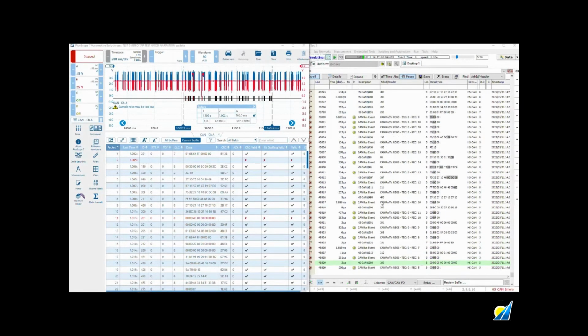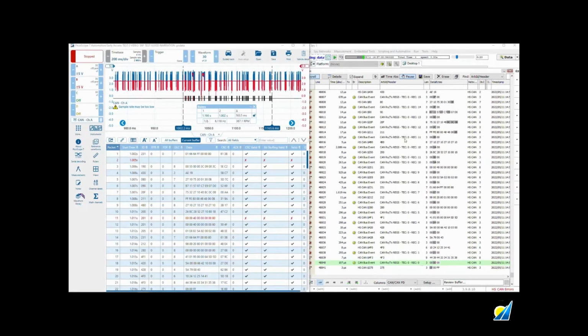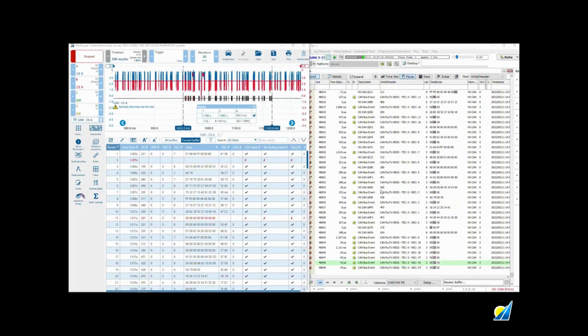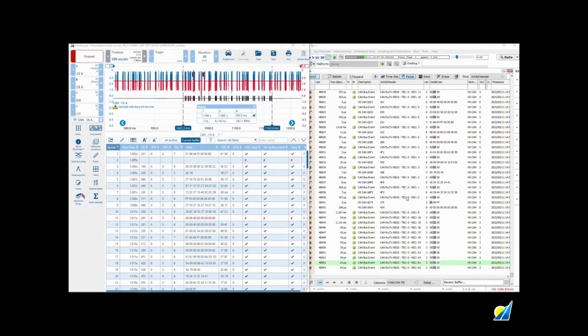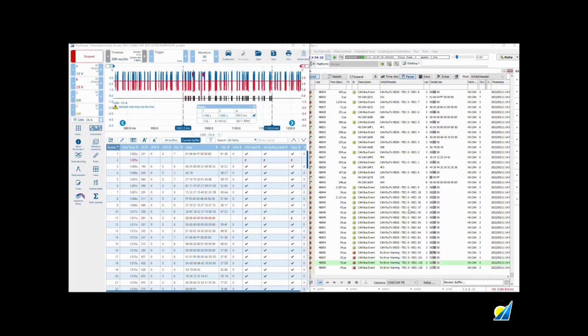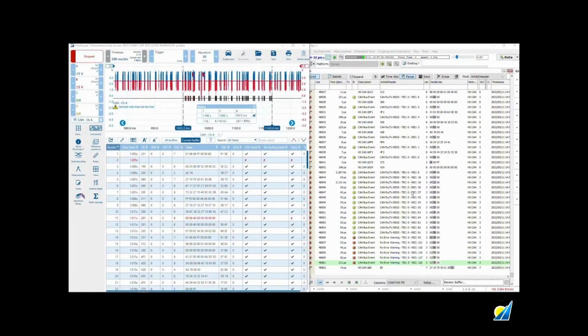Now, as we scroll down, that state changes. First of all, it does increase, and then we start to get successful messages coming through as we described, and the count dropped to 0. Then the bus was restored here. Then all of a sudden the count starts to increase dramatically, and the ratio of these increases differs depending on the condition. So transmit errors will increase at a different rate than receive errors.